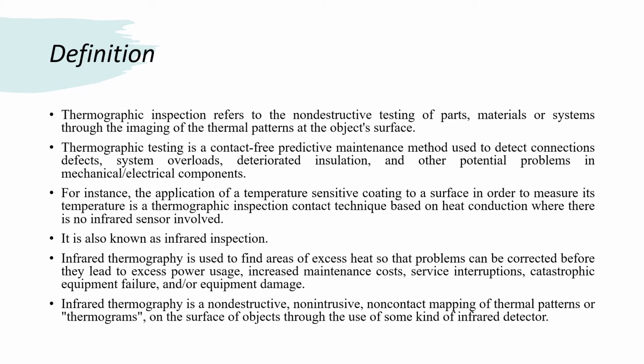This testing is a contact-free predictive maintenance method which is used to detect loose connections, system overloads, deteriorated insulation, and other potential problems in mechanical or electrical components. So this testing is basically a contact-free predictive maintenance method.